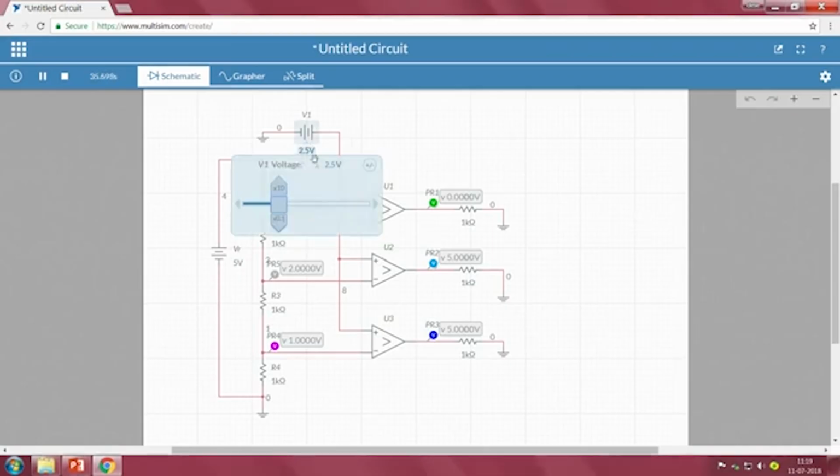Suppose it is greater than 3 volts, so making it 3.5, we can see 5, 5, 5. So 1 1 1 passing through an encoder, you will get 1 1. As a result, we can see how, between these levels, the encoder is converting and giving a digital value: 0 0, 0 1, 1 0 and 1 1, right.